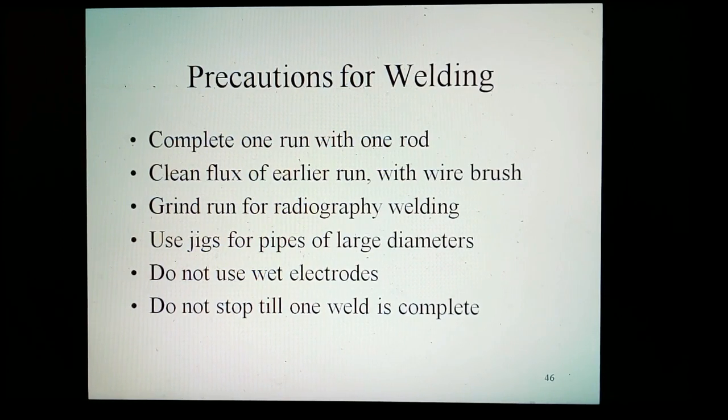Complete one run with one rod. Clean flux of the earlier run with a wire brush. Grind the run for radiography welding. Use tubes for pipes of large diameters. Do not use wet electrodes. Do not stop till one weld is complete.